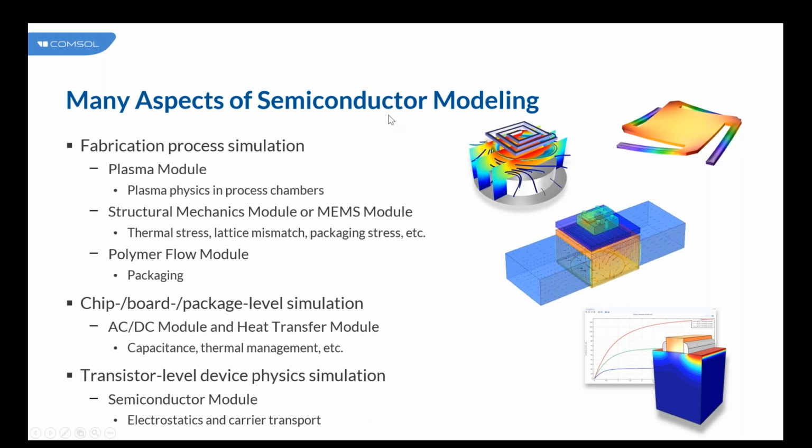For instance, in the fabrication process simulation, you can use our Plasma Module to simulate plasma dynamics in the process chambers. And the Structural Mechanics Module or MEMS Module can simulate thermal stress, lattice mismatch, or the packaging stress that could be caused by all kinds of external loads, or even thermal expansion.